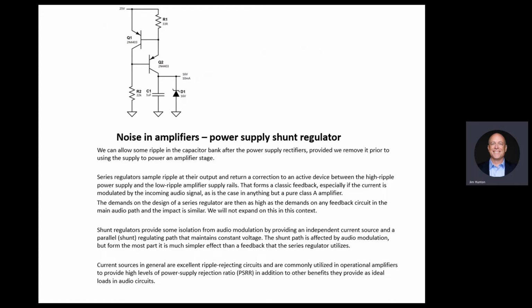So a series regulator is cheap. You can go buy a three terminal silicon thing, easy to use. They work okay. Their frequency response behavior is not as clean as the shunt regulator. The shunt regulator consumes current. So you have a trade-off.